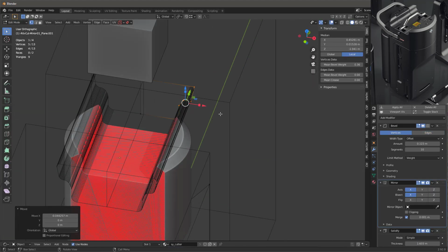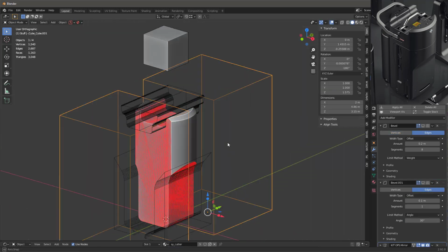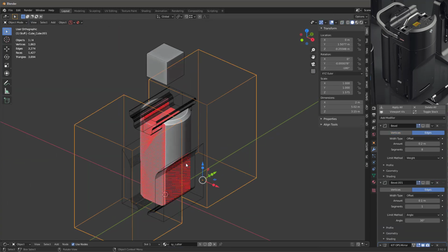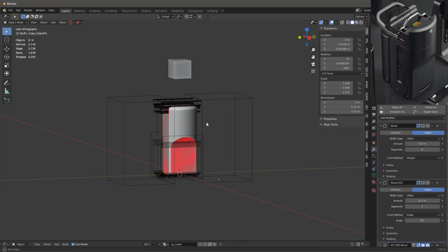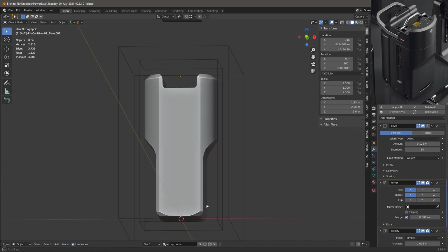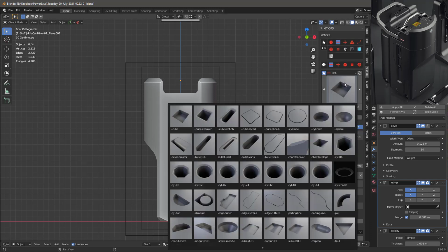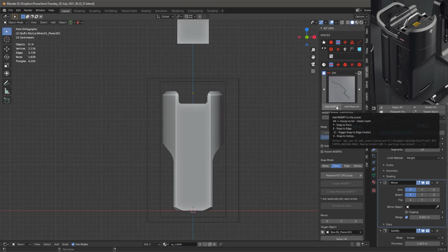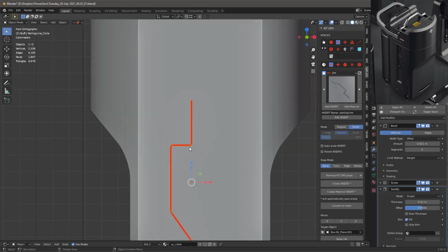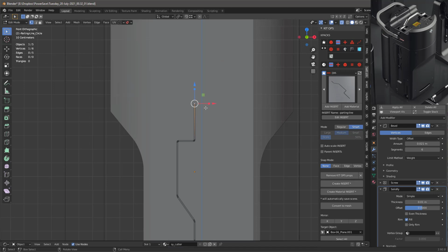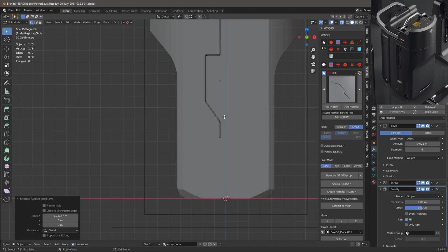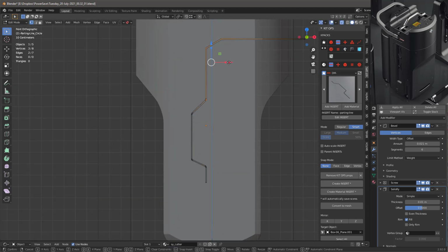As you can see, the red is showing some of the inverted faces, which happens when you Boolean things. A lot of times I want to be able to see those just in case I have an issue with it. And then I'll always use Control-Alt-Shift-Z to hide the viewport for that particular insert and turn it into a bounding box. Now I'm adding another insert, and this is just one that creates parting lines.